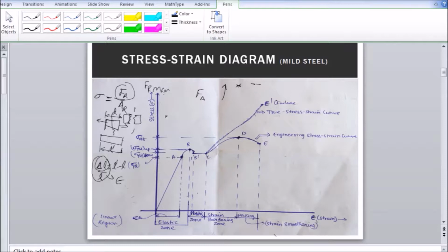Tensile tests are conducted on varied materials, of which the most profoundly used one is mild steel. The tensile test on a mild steel specimen is the one plotted and explained in most textbooks, and it is very important because for this material each point A, B, B dash, C, D is clearly exhibited. For other materials, the stress strain curve is not so clear.